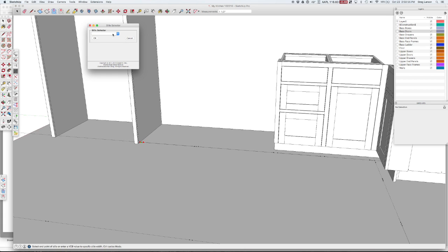So this style, we have a bunch of choices now because I could choose a wall style and it would just not draw the style. I could use a, probably don't want to use a panel or a sheet style. I could even use an opening style. I wouldn't want to use a connector style because I would get those connector holes and I don't really want that. A filler is a nice generic style. I don't really want a blind or a butt because I'll get extended toe kick. So a nice one to use in this particular case is just the filler style.